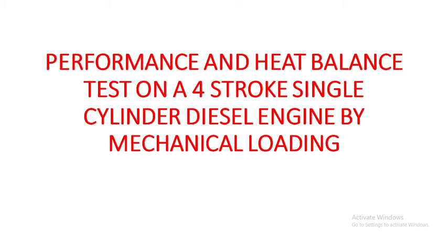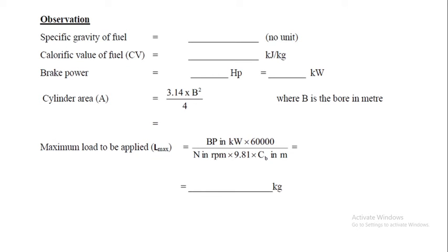So based on this, we will move on to the observations first. Here, the specific gravity of fuel. The fuel is diesel. The specific gravity of fuel is 0.83. Then the calorific value of fuel, we can take the maximum value. It is 45625 kilojoule per kilogram.